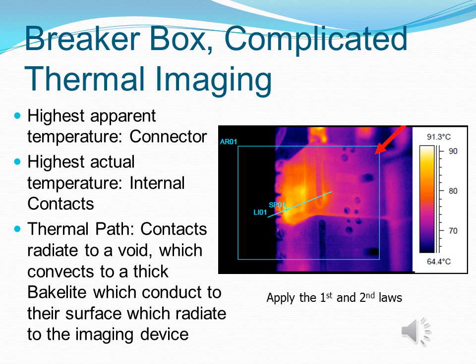However, the internal contact is already probably 100 degrees C above the ambient. It's critical right now. It could fail now. It could blow up or start a fire. Most likely it'll keep tripping this device, and they won't know why the device is tripping. Well, the device is failing, and that's better than causing your system to fail in some other way. That's what the breaker is there for. This breaker box needs to be replaced, and it needs to be replaced now. In this case, it's tripping constantly. That's better than the other alternatives.